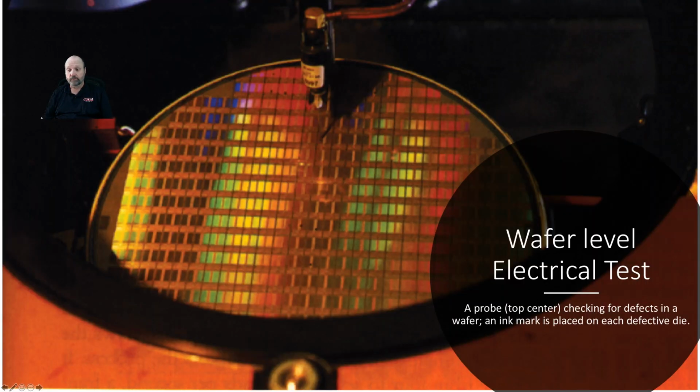All right, so we have wafer level electrical tests that we do, and this is actually labeled a little incorrectly. This is taken out of the book. They've already done the electrical tests on all the chips on the wafer, and then they follow it up with an ink probe, and they're inking the die that are bad. So you can see a few ink dots showing where there's a bad die. That was the old school way of doing it. You would just mark the bad ones so that the machine vision systems later on wouldn't package the bad die, the ones with the black dots on them.